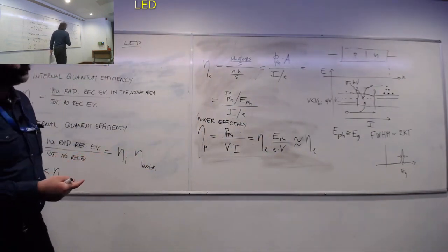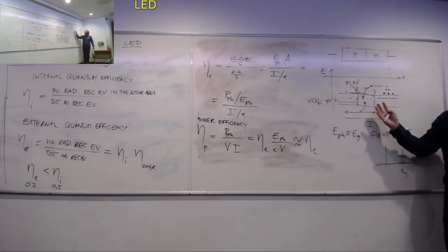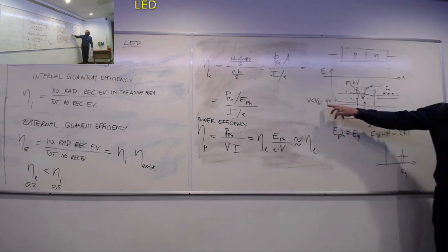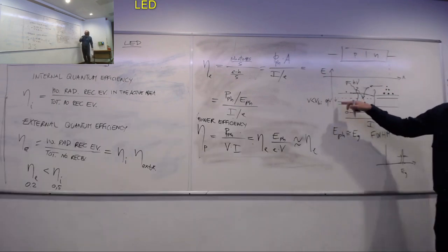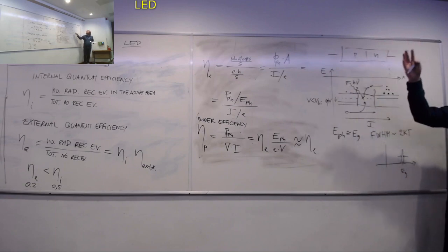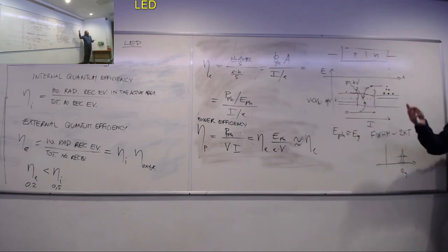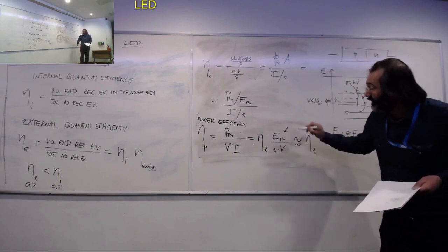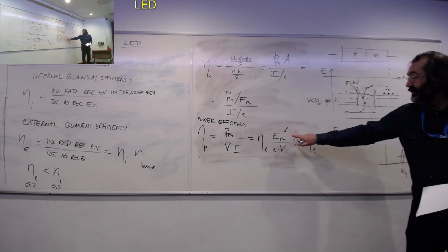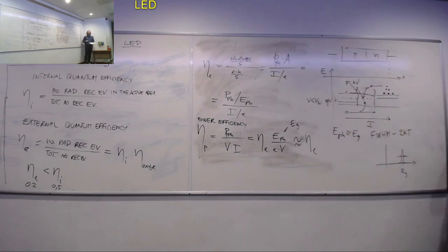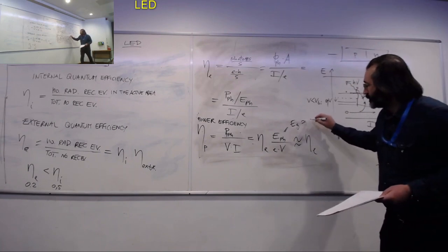And the reason is that, as you can also guess from here, when the pin junction, the LED, is forward biased, the quantity QV is roughly very close to QVBI. The current grows a lot. So more or less, we know that when it's forward biased, the voltage we are applying will be very close to VBI anyway. And we can show, as we've said previously, the photon energy is roughly EG, and EG, this is what we demonstrated, we mentioned maybe when we did the pin junction, EG is very close to QVBI.